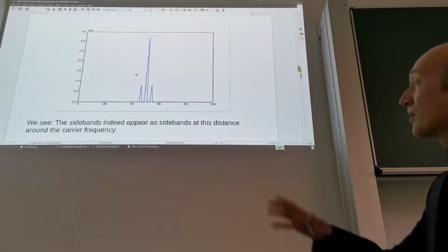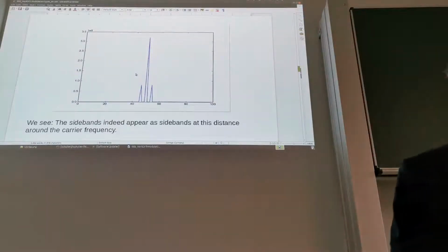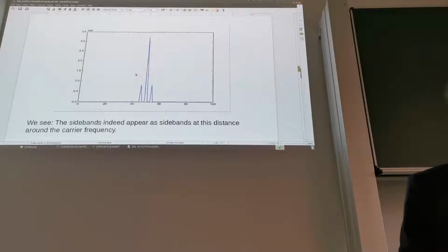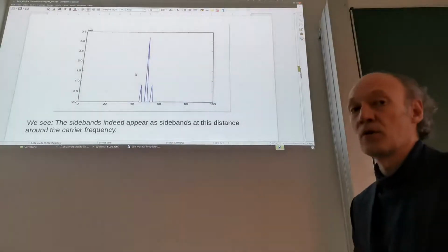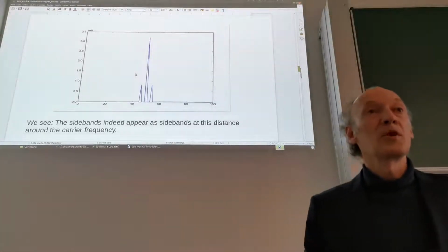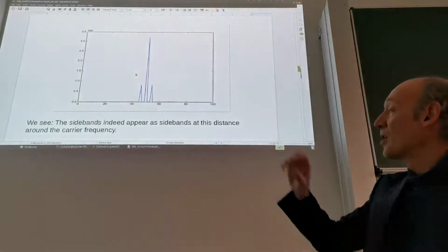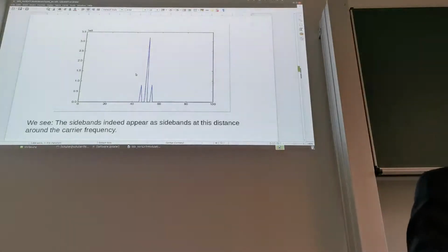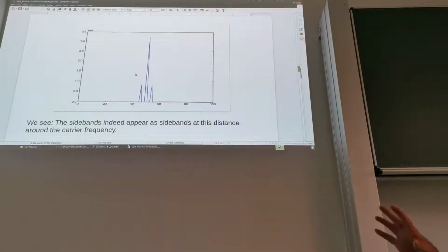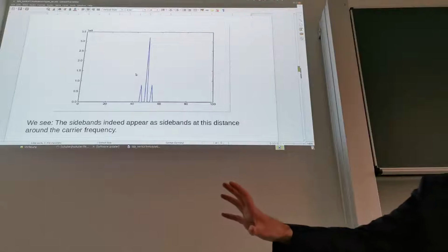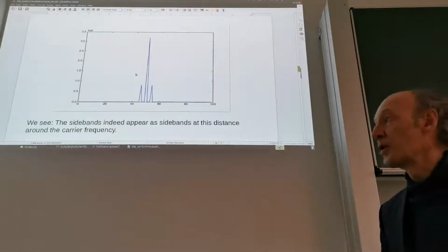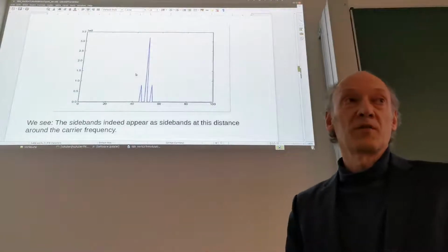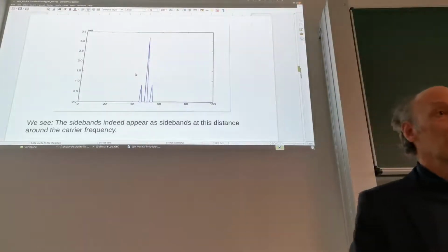And the carrier is just good for a simple demodulation in the receiver. Demodulation in the receiver is basically a mixing of this AM signal with its own carrier. And mixing with its own carrier means we also have a component which is back at the baseband, and then we just need to apply low-pass filtering to keep this part at the baseband to have the demodulated signal.